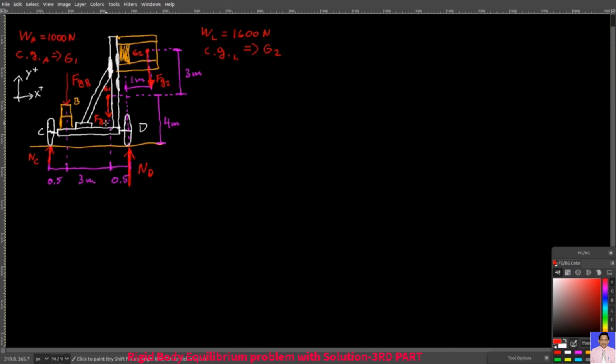And so, if you don't have enough blocks at B, then Fg2 might cause the platform to tip over at point D due to a clockwise moment about that point. Fg1 would counter that a bit by providing a counterclockwise moment about that point, but it would not be enough.